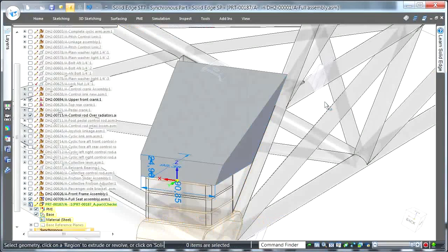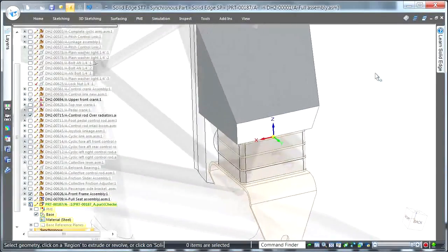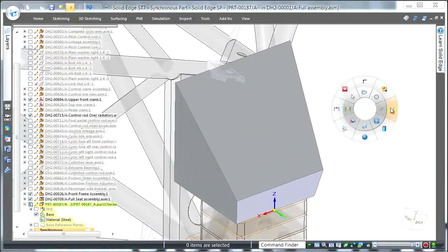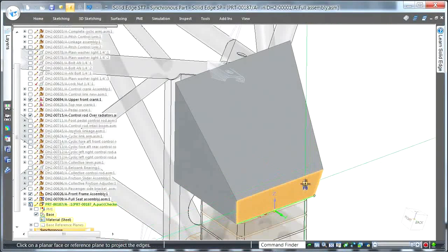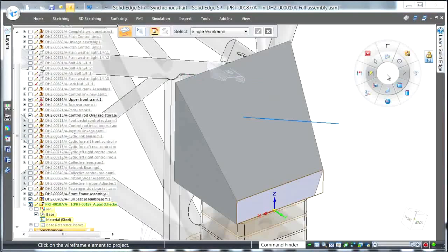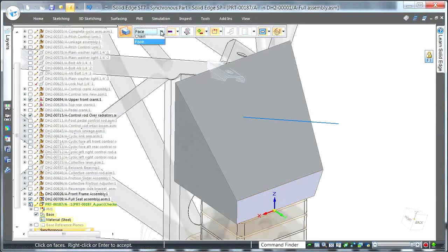We could maybe take that little top bracket as well. We could just take the sketch location off the top of it, and then we can put a little cut in on the top. So what started out as a very simple shape, you can do very quick edits using synchronous technology to get more of a complex shape, and it'll be cool to see exactly where we're going with this later on. Another quick shape is the cylinder.